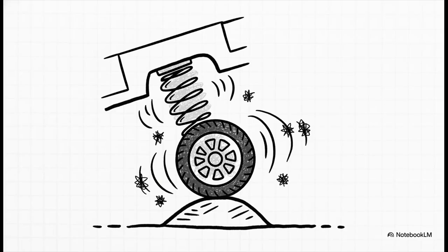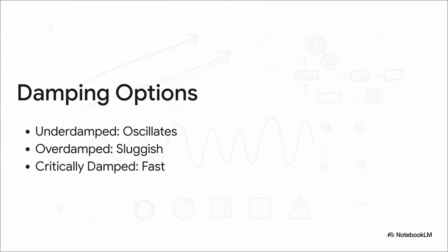But a second-order response? That's fundamentally different because it introduces a brand new physical property to the mix: inertia. It's not just a simple tank filling anymore. It's a lot more like a car's suspension hitting a speed bump. You see this when you have 2 first-order elements interacting, or mechanical components with actual mass that resist speeding up and slowing down. And because of that inertia, a second-order system gives you, well, complications.